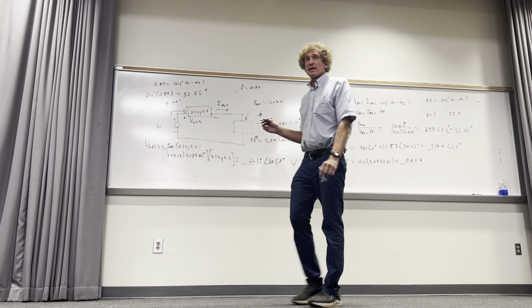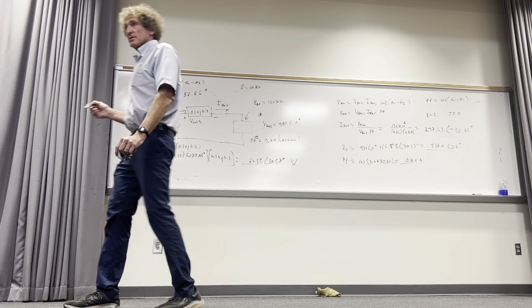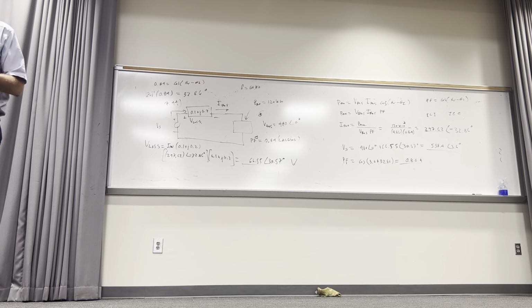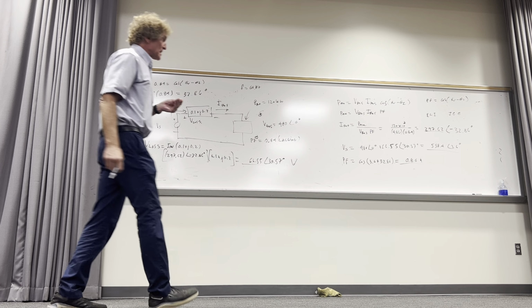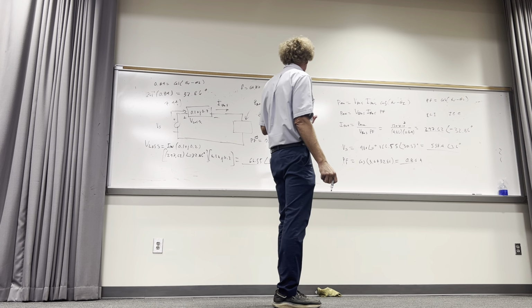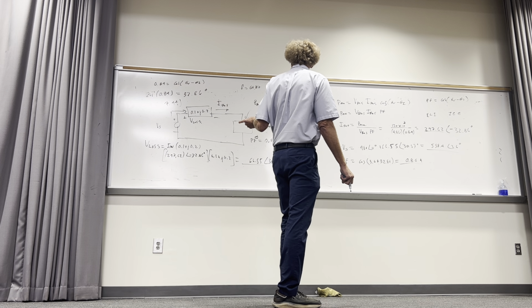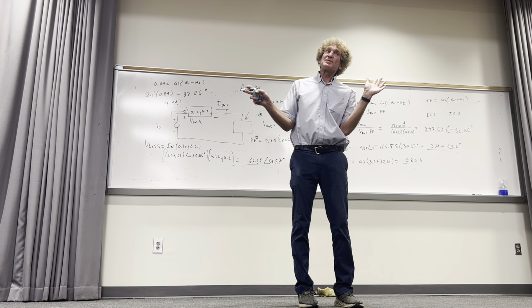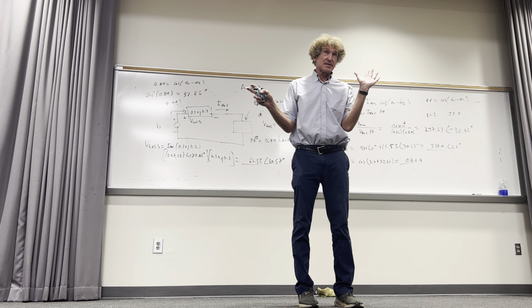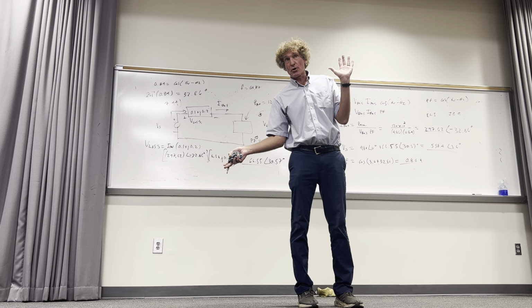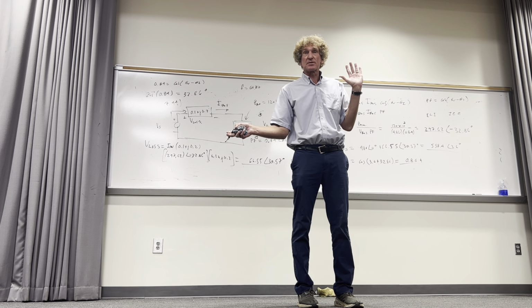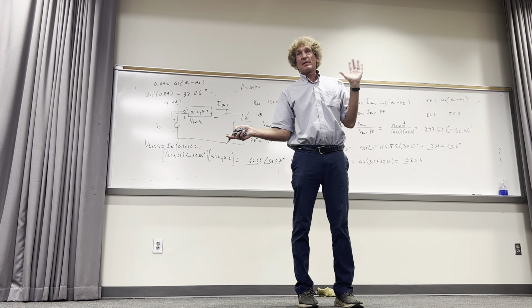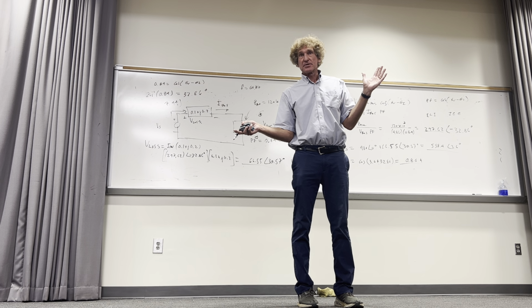Is it lagging or leading, and why? I'm asking you now. Think. Well, the voltage angle is what? 3.6. The current angle is minus 32. Obviously, the voltage angle is ahead. Do you all see this, class? So it is lagging. The lag has to do with the current's location relative to the voltage location, you might say the angular location. You all with me, class?